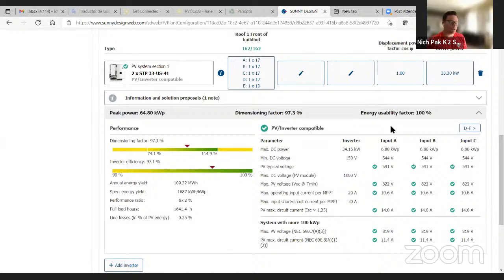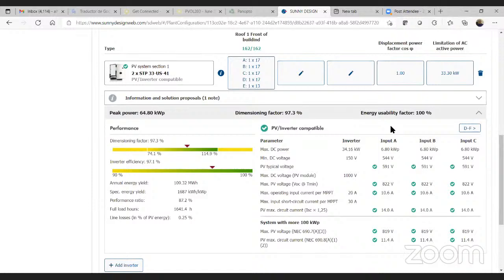Excellent, excellent. We had a question about rapid shutdown too. What accessories and components are used for rapid shutdown in a system setting of this nature, like a flat roof commercial setting? This is an absolutely great question, and I would love to take the opportunity to drive people to the SMA-America.com website. The Core 1 US-41 line of inverters has a SunSpec certified transmitter built into it. And so there are receivers that are certified by sunspec.org to comply with their open standard for rapid shutdown signaling. However, that certification covers just rapid shutdown signaling.